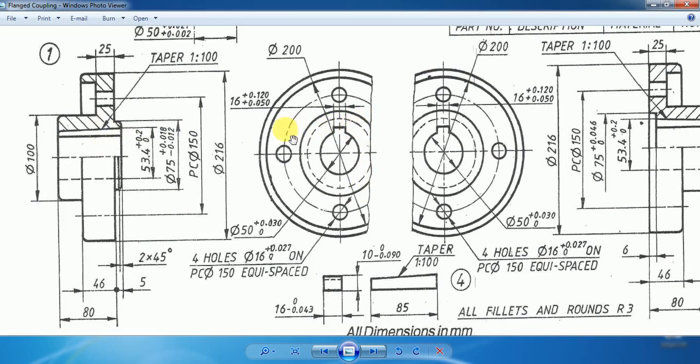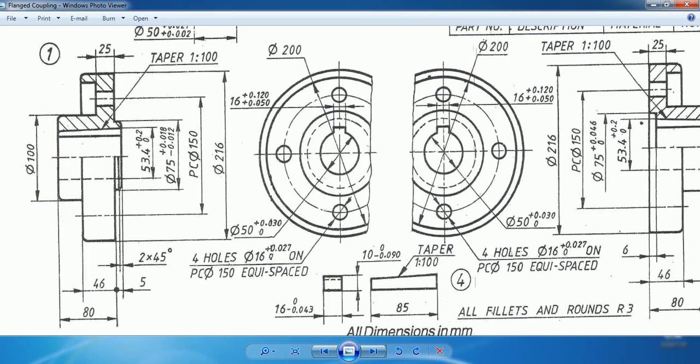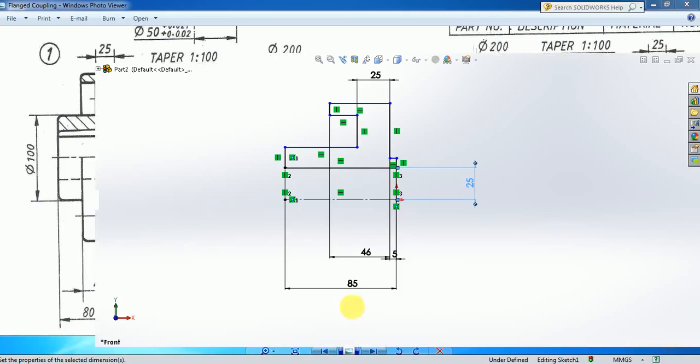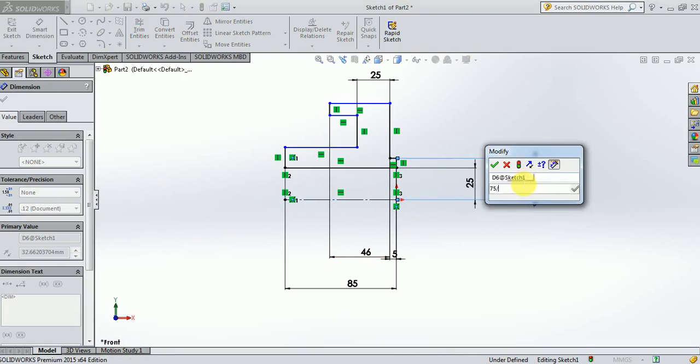Okay, so as you can see here, this dashed circle is going to match with this one. So that is the diameter of 75 mm. If you extend the horizontal line here, this dashed circle corresponds to a diameter of 75 mm in the front view, that is this distance. So therefore what I do now is I'm going to give the distance between this point and this axis as 75 by 2.